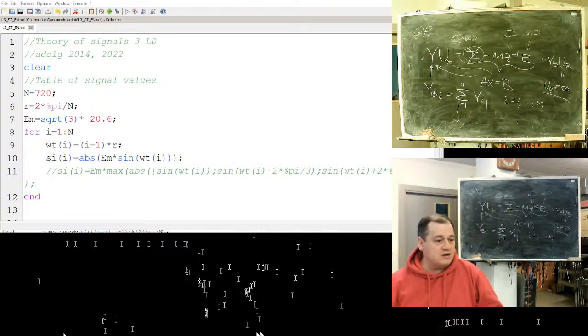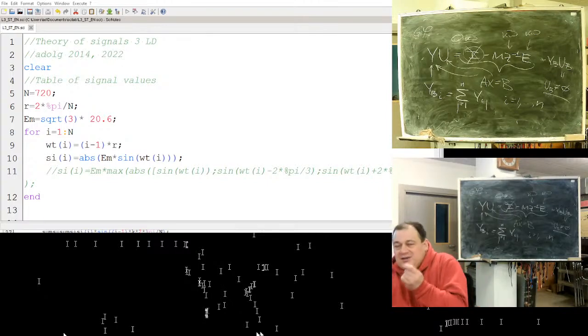Only the schematic is enough. And we just need to do the same thing, right? Yeah, the same thing. It's a schematic without numbers, so you can choose numbers at your will. Why? Because you can set them as you wish. The element numbers are not important. We need element values, but the numbers themselves are not important. They are only important in how they are put in the matrix.